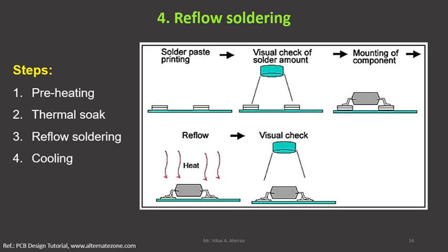So when that PCB passes through this heating zone, the reflow of the solder metal will take place because that heat will be sufficient to melt the solder paste, and that will cause the soldering process. After this, you may check once again the soldering quality through a visual check.